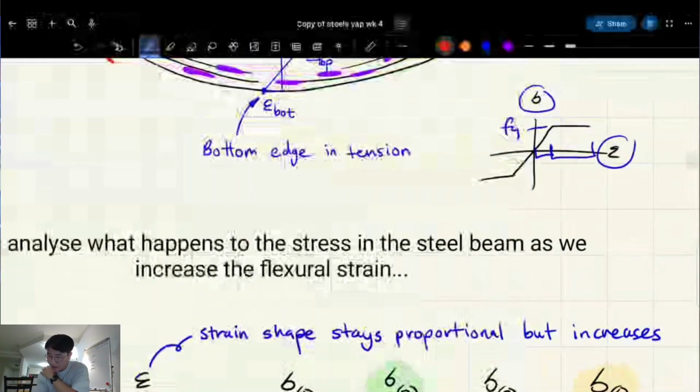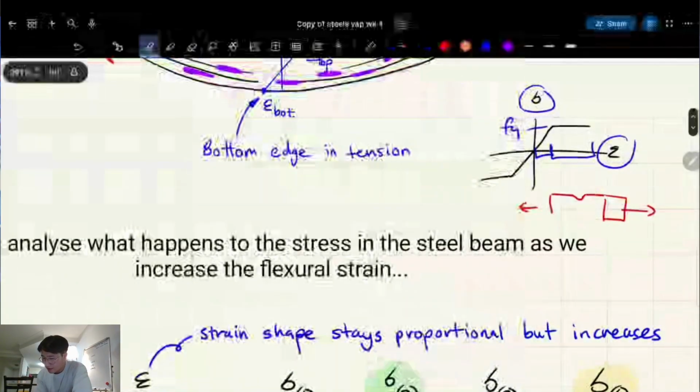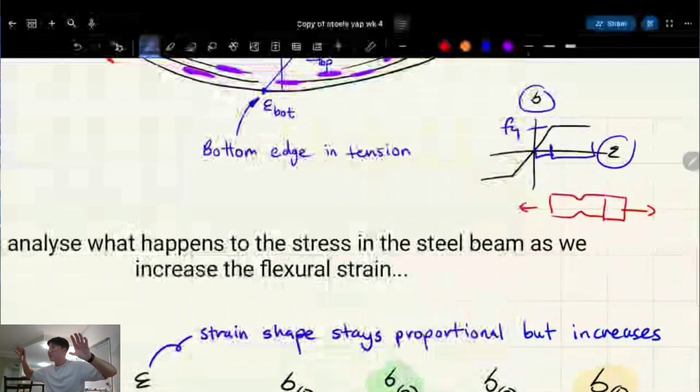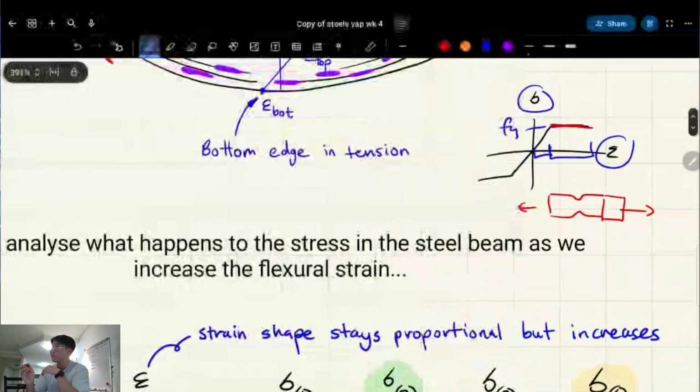So what happens in the apparatus, right? Let's just say I don't know what shape it would be, let's pretend it's like that, and it's being pulled apart. Let's say in tension, because tension's easier to test for. It keeps pulling and gives a linear amount of increased resistance as you strain it. But once it reaches yielding, it starts doing this kind of cheese melt thing as you keep increasing the strain, and the rate at which it melts like cheese makes sure that the resistance is this plateaued amount. Does that make sense?